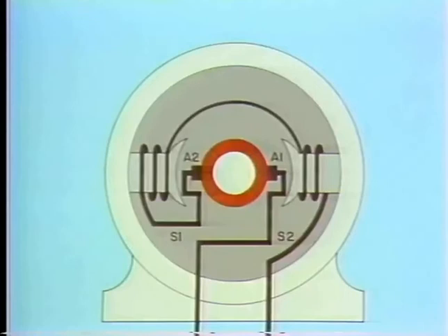Now, we're going to use diagrams or schematics of motors to show you how to identify them. DC motors are classified in a number of ways, but the most common way is according to what type of field winding they've got and the way their fields are connected. This is an illustration of a series motor. It's about the simplest kind of motor you'll come across. The field coils, which we call the series field, and the armature are connected in series with each other, and there's only one path for current flow.